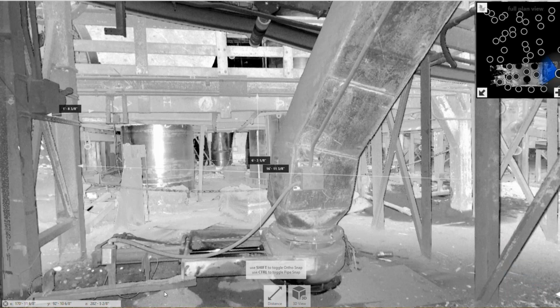But the main thing is, if it's a wide open space, like a warehouse with nothing in it, then you can see most of the building in 2 or 3 or 4 or 5 scans. If you are in a congested area and you want the details of that area, then you have to look at your line of sight and determine how many scans you need. You walk from each position and ask, am I getting the details I need for my design?